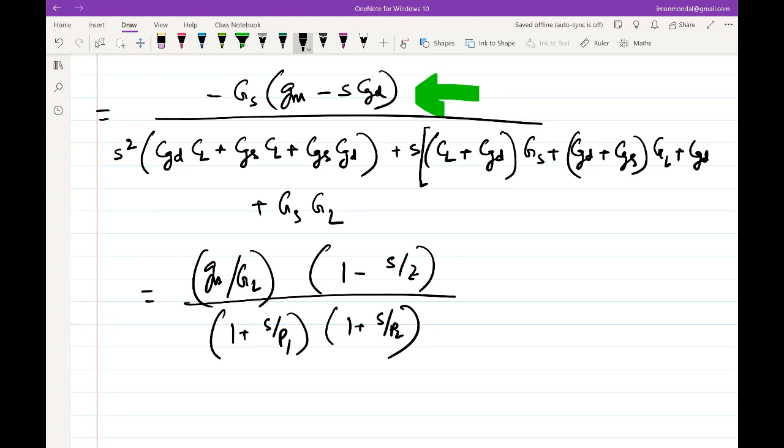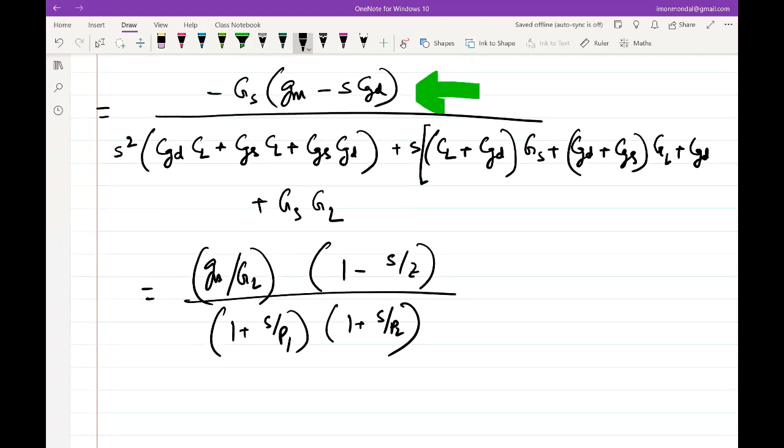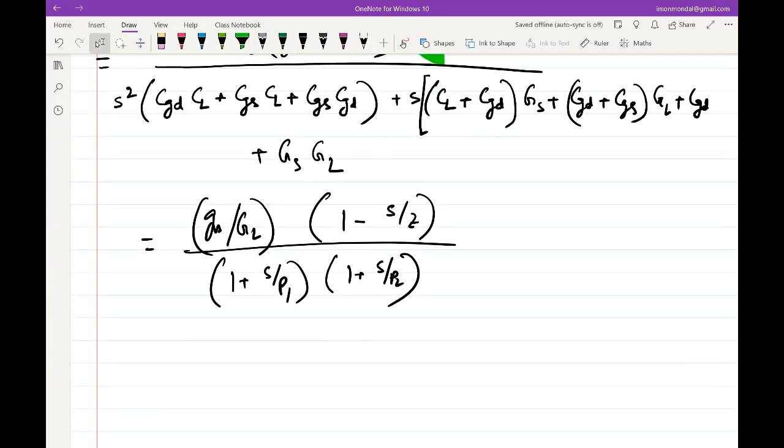But I'll go mad, right? So if I do quadratic on this, we'll do approximation, right? We can do certain approximation based on the assumption that the poles are nearby or poles are far apart, right? We have done it once already. So let's use that, right? Let's assume, again, there is no basis of assumption till right now because we don't know much. So we'll assume something and go back and verify whether the assumption is correct or not. Okay, so let's assume something that poles are far apart, right? So assume poles are far apart. Assume P1 is much less than P2.